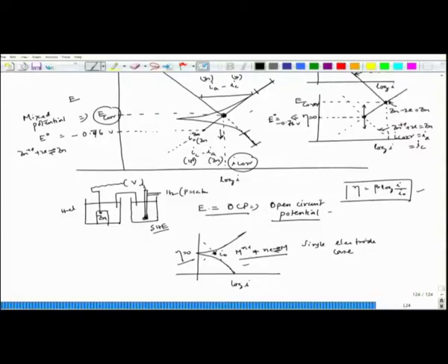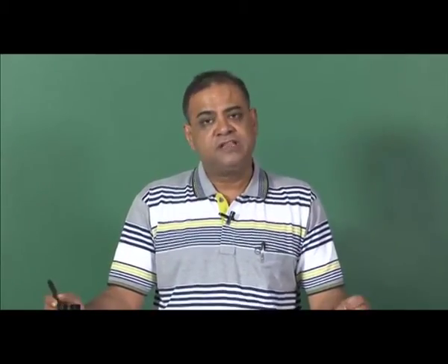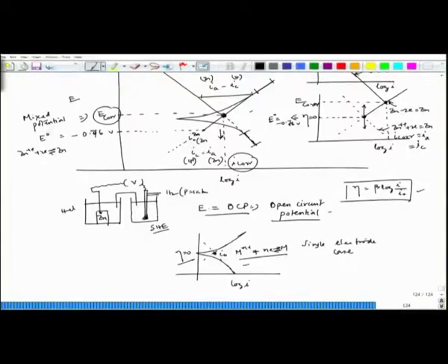One is a single cathodic reaction, another is a single anodic reaction. Once we reach the mixed potential, I could see that if it is an isolated metal block in that particular solution, there is no net current flow, and that is achieved when I_A equals I_C at this point. That is what we have understood in this particular diagram.